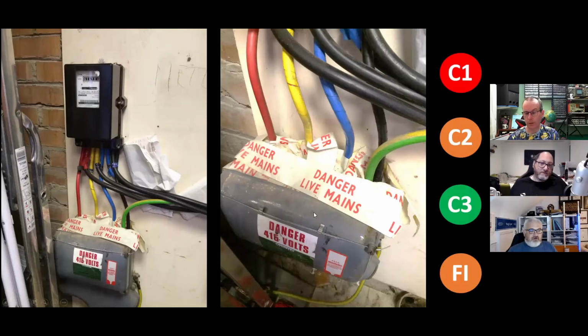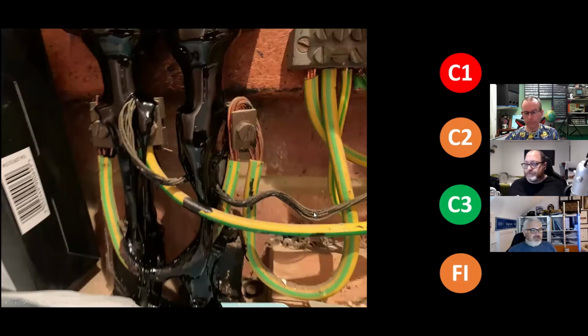Right. Next one. Ooh, this is a classic. So this is a looped service. This is where the service and a domestic incomer will come into a cutout. It will then supply you and your fuse. That connection will then be made to come back down via a cable, punch through and go into next door. It was basically a money-saving thing in decades gone by where they could save money on cable. It's a bit of a nuisance because if your next door neighbour goes down and you're looped off of it, you're at the behest of them.